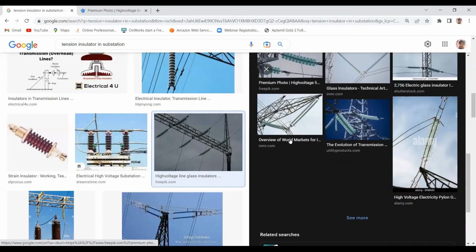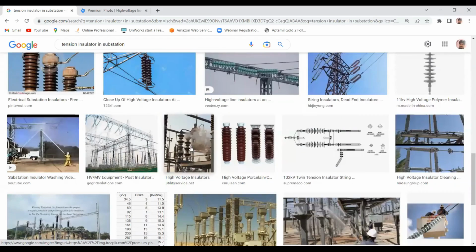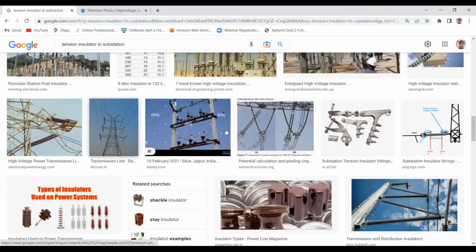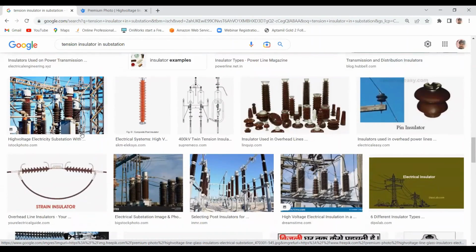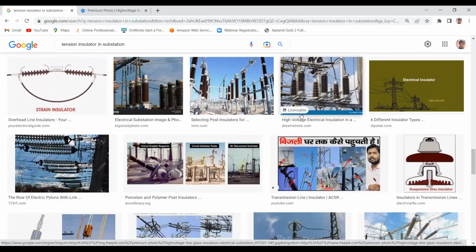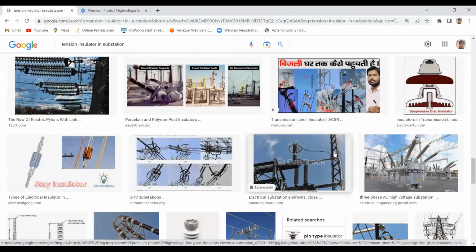So that's about this clamps and connectors stream. Clamps and connectors are also very, very important because this will create a headache at the last commissioning stages. The clamps will not fit. So it's very, very important when you are preparing the bill of material for the clamps and connectors, to check once or twice and thrice whether you have given a good size of clamps and connectors suitable for that conductor.